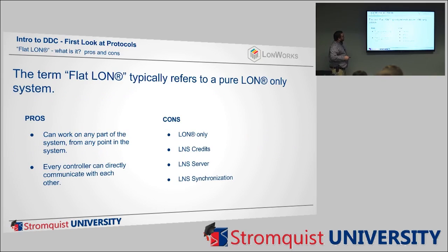One thing you'll hear in LON is the term flat LON. Flat LON is not the Niagara-based LON, it's the LON that Echelon developed. It's a truly open LON system where everything in the whole system is LONWORKS, which is great for a building where you're coming right out of the ground and you can say, I want everything LON, and I don't care if it's Trane LON, Honeywell LON or Johnson LON, it's all LON. It all meets these very strict requirements, and it all talks.